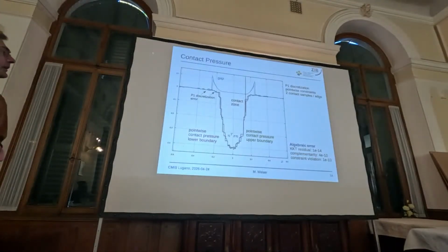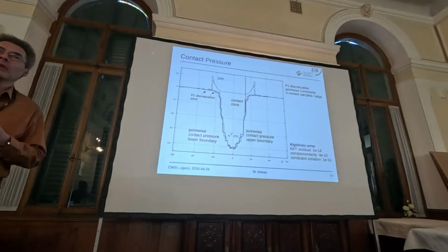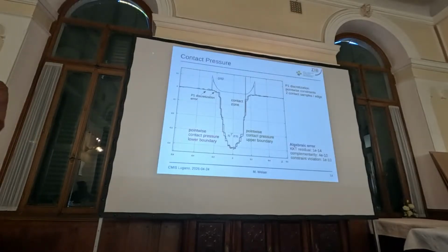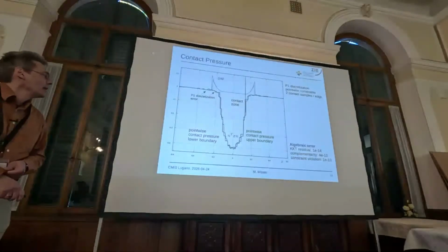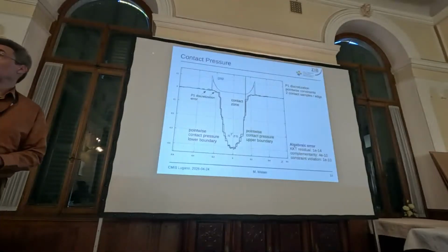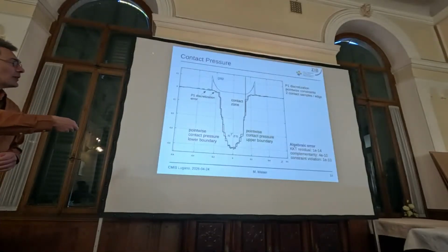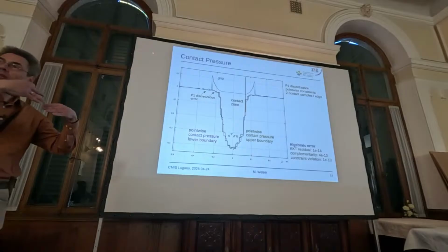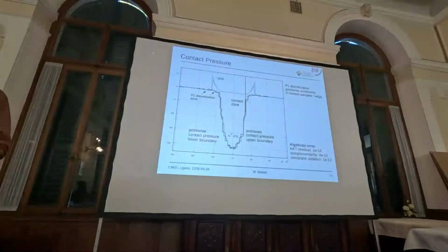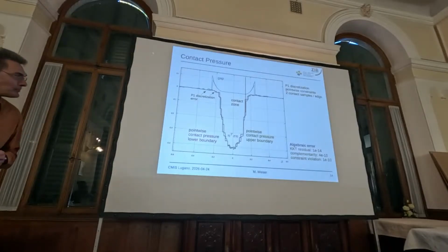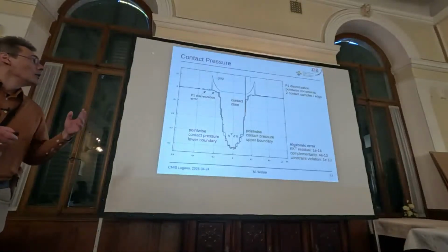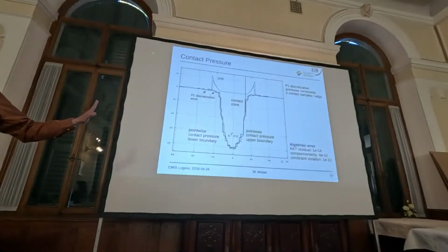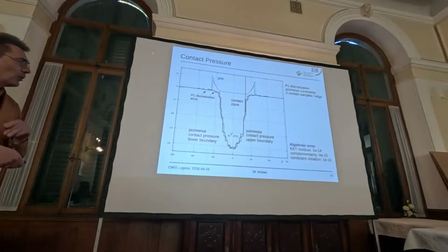Of course, this looks quite ugly, right? No one would complain against that statement. This is because this contact pressure on both sides is recovered from the piecewise constant stress in the piecewise linear finite element. And then, of course, this is piecewise constant here. So why is that looking so ugly and noisy?